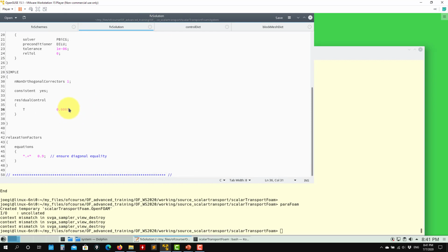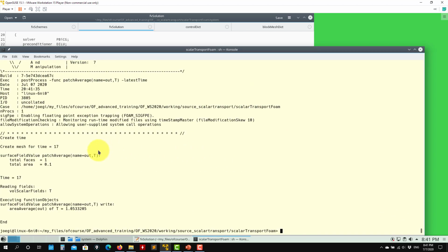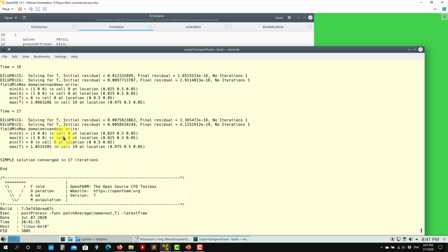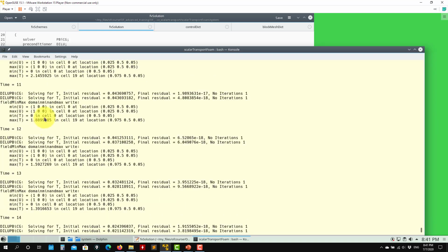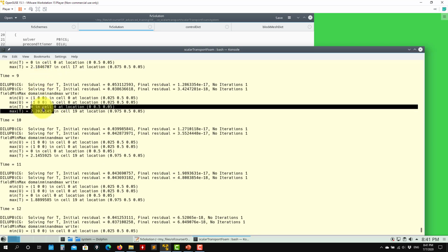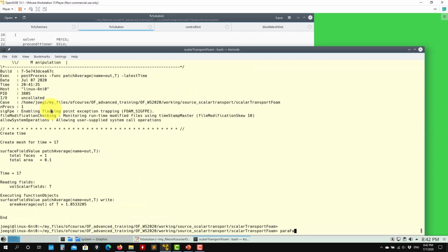And here, let me put this one 0.1 and put this one 0.7. So if I run this case, okay, see that in 17 iterations it's stopping, but see that now at the outlet, when I measure that quantity, that should be 1. I have here an error that is about 10%. This is a large error, and this is not acceptable, okay? But here you can see that there is a fluctuation. See that in one point it is going to 2, that in reality shouldn't happen because we have that source term there.